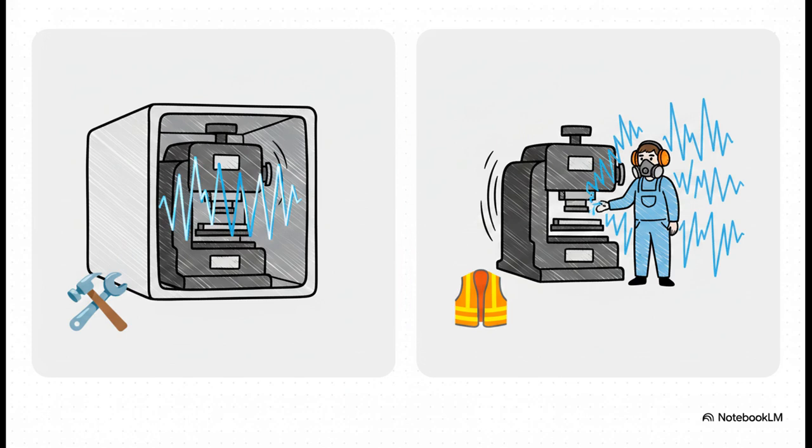It's the difference between engineering controls and administrative controls, or PPE. Administrative strategies basically just manage the exposed worker, right? It's giving them earplugs to survive a deafening room. But engineering controls, they actually fix the source. We literally engineer the machine to be quiet in the first place. It's fascinating because eliminating danger at its origin heavily outranks just handing someone protective gear.